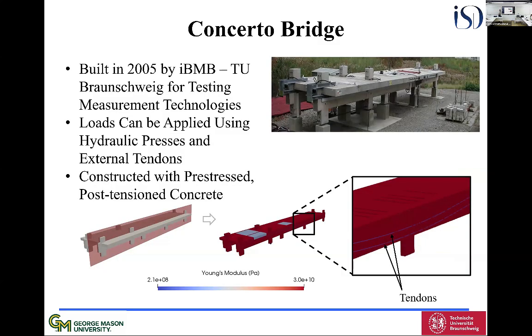And this is now a more ambitious case. This is a bridge that is measured in Braunschweig. You can see it's a concrete bridge with pre-stressed, and there are trusses here at the bottom that you can pull in order to load the bridge. And over the years, they have actually weakened artificially these two regions here by putting chlorine and salt on it so that the concrete weakens.